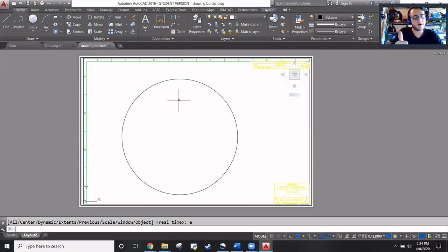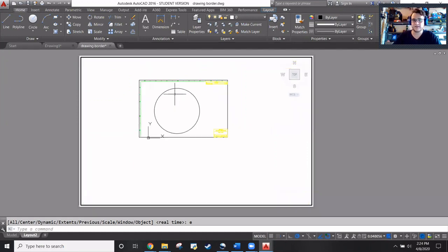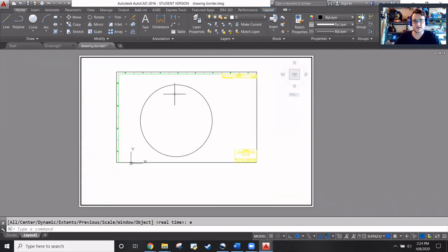So the only other part of this is once you're done modifying that zoom, you need to go back into paper space in the layout, because right now I'm tunneled into the model space. And I don't want to stay tunneled into the model space, because if I stay tunneled in and I zoom out, it's going to resize my drawings, right? This is definitely a top 5 most common mistake I've seen in AutoCAD. I've done it myself many times, and it's super annoying because you'll print a 50-page drawing set to PDF, which takes forever, and then there's 1 or 2 drawings that are zoomed out like this, and you have to go back and fix it and do the whole thing over again. It's a huge pain in the ass.